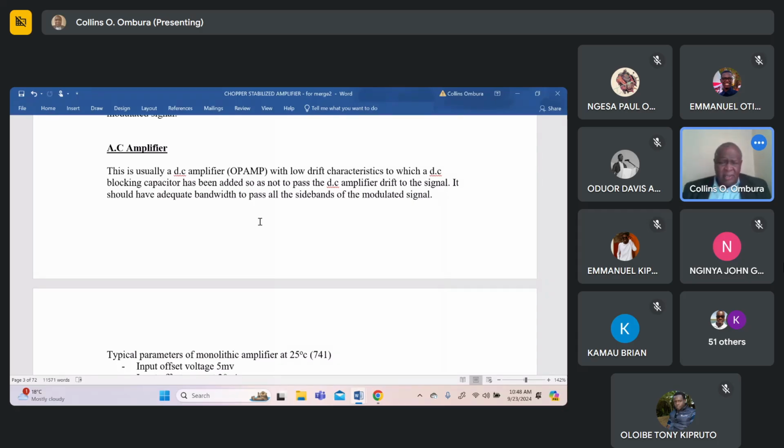So there'll be very little interference if the system is designed properly. And if you are scared of radiation, then you can use electromagnetic shielding. You can put your amplifier inside a metal case or a metal foil. And that's what they do. If you've got a high quality laptop and you break open the power bricks, you'll find an aluminum shield inside that prevents electromagnetic radiation due to switching from interfering with things like radios, televisions, mainly communication equipment.